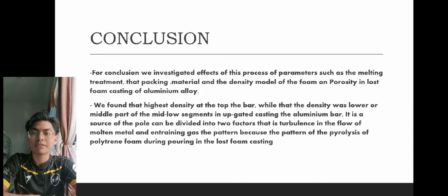Now I will continue the presentation by presenting the conclusion for lost foam casting. For the conclusion, we investigated the effect of process parameters such as the melting treatment, bed packing material and density of the foam model on porosity in lost foam casting of aluminium alloy.